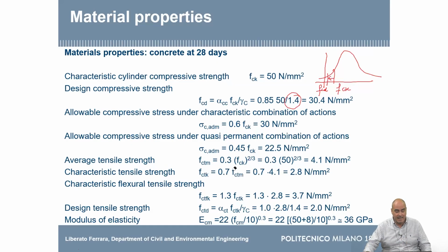And you see the tensile strength of concrete does not depend linearly on the compressive strength. It has been found, or it has been set. Well, this is the Eurocode. I think that the ACI code uses the square root here. But in the Eurocode, we have the cubic root of the square, so it's like power 0.67. And there is a coefficient here, 0.3. This is a best fitting. There is no physics behind this. Well, the only physics is that they do not depend linearly on each other.